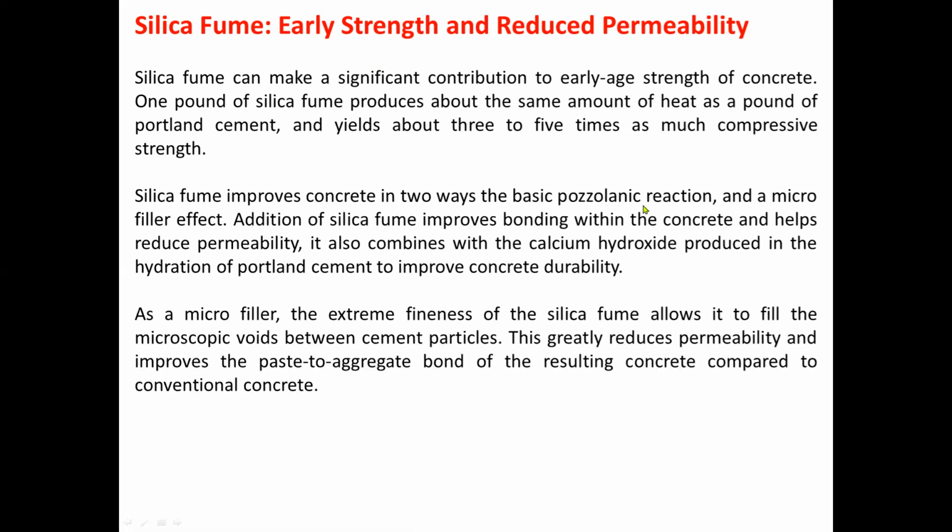What else? As a micro filler, the extreme fineness of the silica fume allows it to fill the microscopic voids between cement particles. This greatly reduces permeability and improves the paste to aggregate bond of the resulting concrete compared to conventional concrete.